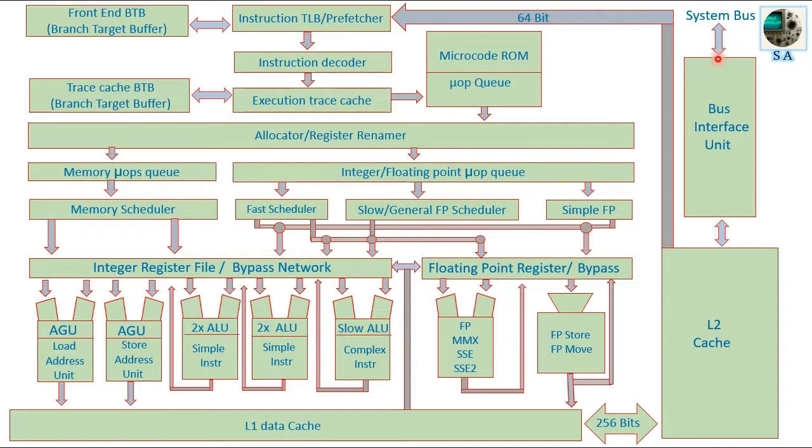The processor connects to the outside world through the bus interface unit. The concept of cache memory is very important. The external dynamic RAM runs at far lower speed than the internal microprocessor logic circuit and clock. So if the CPU tried to fetch instructions from external dynamic RAM every time, that would slow down and drop microprocessor performance a lot.